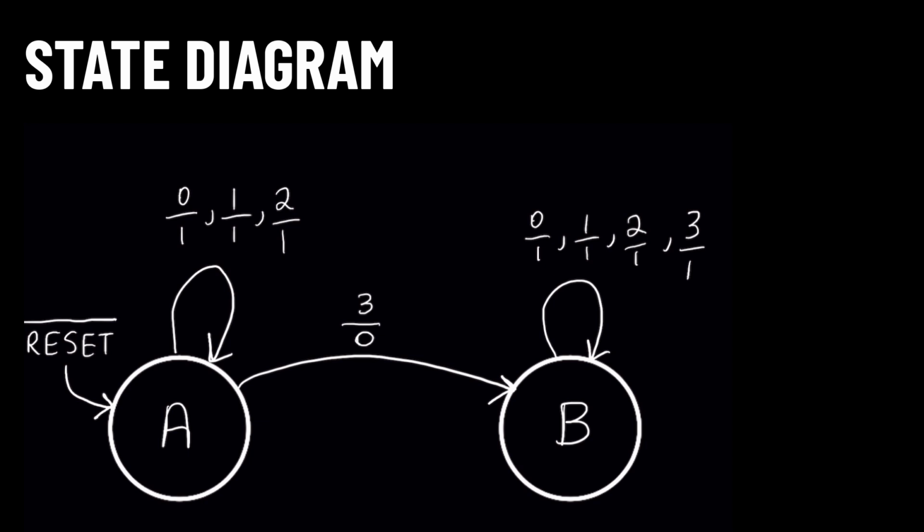Our state diagram is fully defined because every input value, there are 4 because we have a 2-bit input, has a clearly defined transition on the state diagram, and each of those transitions has a defined output value. There are no input conditions that would lead to an unknown outcome.